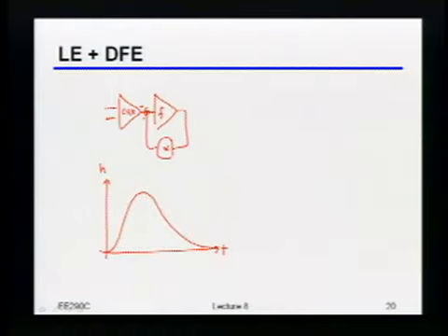Well, when I apply just the continuous time linear equalizer, keeping in mind that when you apply linear equalization, that generally means that you have to throw away DC gain. What would the response look like, and let me maybe draw where the sample points are here. Let's say the sample points are something like this, okay? Roughly speaking, if I just did everything with a linear equalizer, what would that new response look like? Or what would you want it to look like? And okay, maybe there's even a precursor here. So what should that new response look like, just qualitatively?